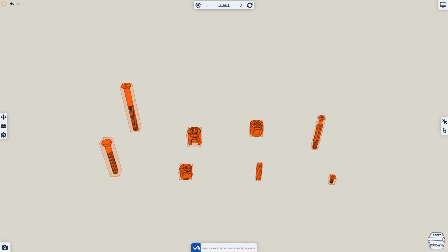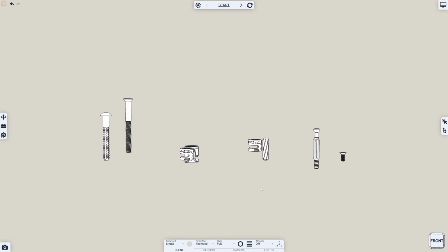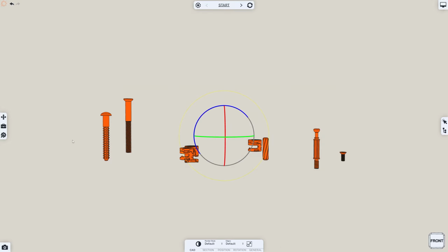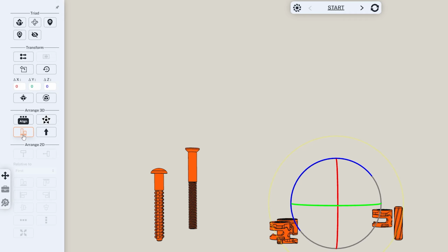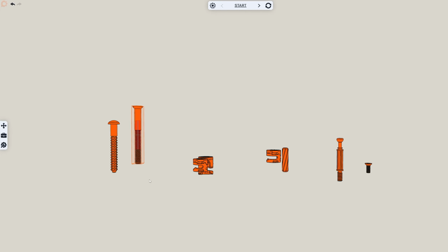When you create a layout, all items start at the same level. However, after rotating or manually moving parts, they can drift out of alignment. The Align tool helps ensure everything sits neatly on the same plane. Select the objects you want to align. Your first selection becomes the reference. A bounding box and mid-planes appear, and you can choose which surface or plane the rest should align to.